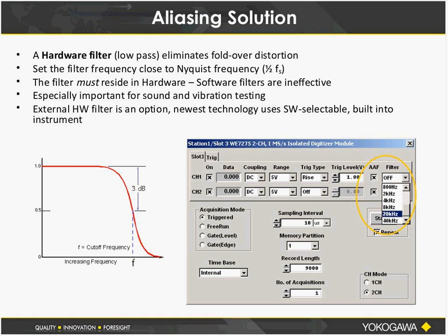And if this type of noise is important to you, if you want to deal with it by using an anti-aliasing filter, you have to check to see if your instrument or your digitizer has one, or add one in front of the signal before the A to D converter. What is an anti-aliasing filter?